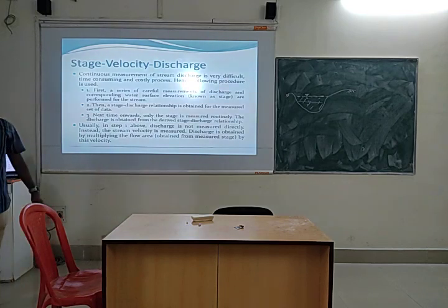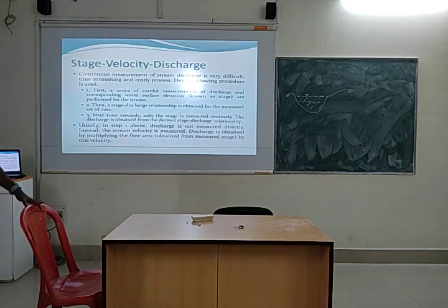Next, from the next time onwards, only the stage is measured routinely. We will get the stage, and according to the stage we can find out what is the discharge.